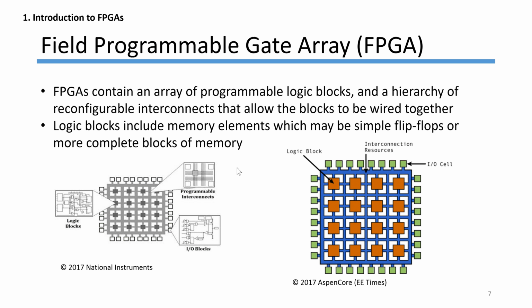Field Programmable Gate Array. These are colloquially known as FPGAs. FPGAs contain an array of programmable logic blocks and a hierarchy of reconfigurable interconnects that allow the blocks to be wired together. So if you can see these 2 images down at the bottom, you individually design these logic blocks and program them, and then as you are translating your program into the chip itself, these interconnection resources then start wiring the different logic blocks together.